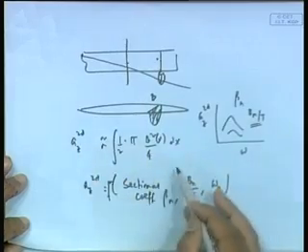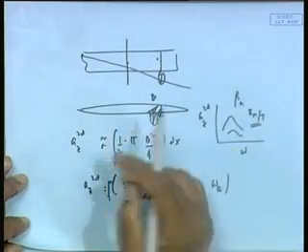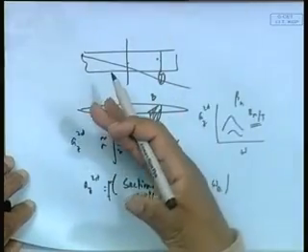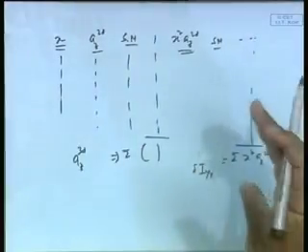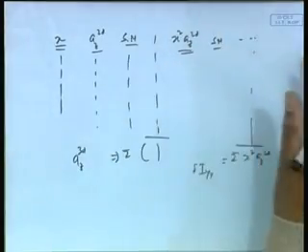Anyhow, this is only an estimate I am focusing on, so that you get a rough idea. As I mentioned repeatedly, somebody comes to your company, you are in a shipyard, and they ask you for a guess of the natural period, etc. You can quickly use this added mass and moment of inertia part, the high frequency formula. It is slightly better than using a ky equal to 1 or some factor, slightly more accurate. So these are all various levels of approximation that you should know.